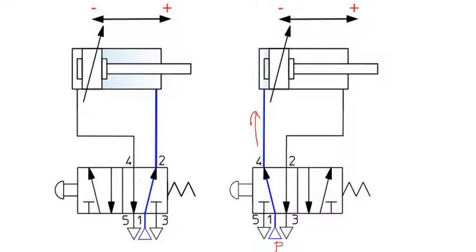From the pump, the fluid moves like this and connects the pipeline towards the actuator, and the liquid force acts on this piston like this. The piston travels outward, and whatever liquid accumulated over here travels like this, connects like this, and this is for the reservoir. It happens during the extension stroke. Here, plus indicates the extension stroke.